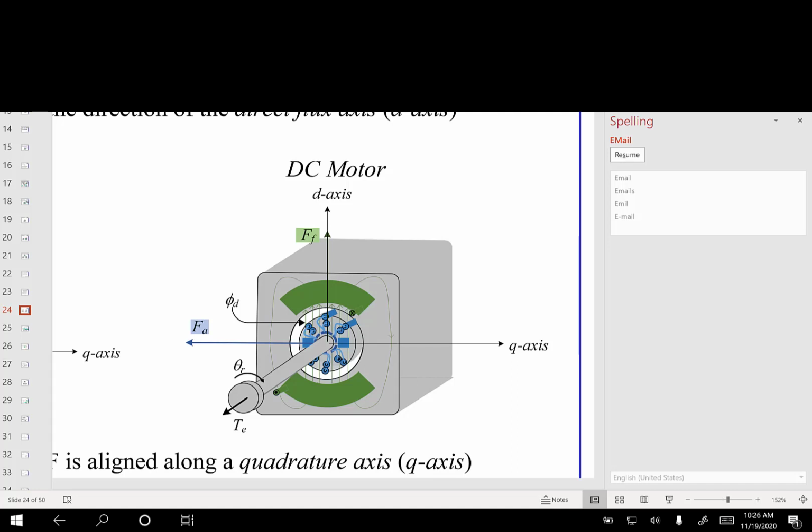And the field winding is what you're really trying to align your armature winding with to get torque. And since my field winding is on the stator, the MMF is not moving. That's why I have to have the commutators: from the perspective of the field winding, it has to look like the armature is at a fixed angle.